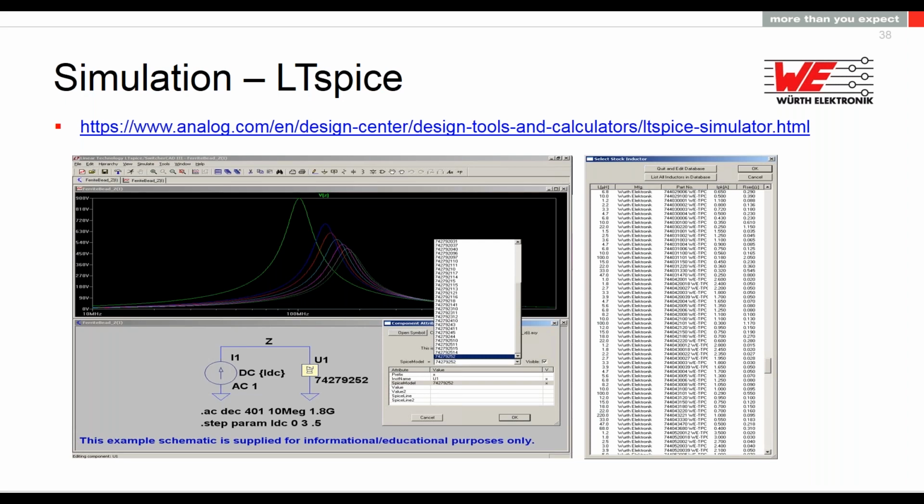If you have the model of your transformer, well, we have a model for our transformer, and if you use our transformer with the chip and with the common mode choke, and you have a model for the Lisn, it is quite complicated to get it, but it's possible. If you just measure it with a network analyzer and have the S parameters of that, you can introduce a box and load the S parameters there. You can predict conducted emission already with LTspice.